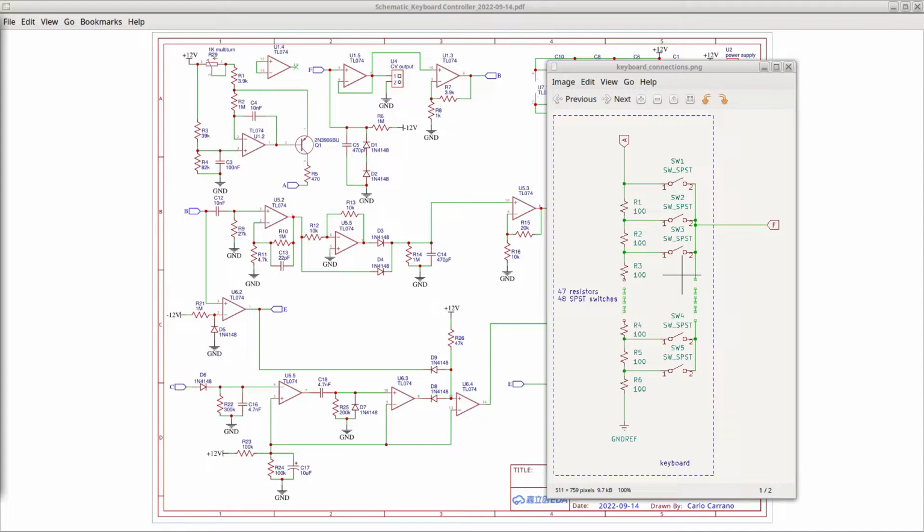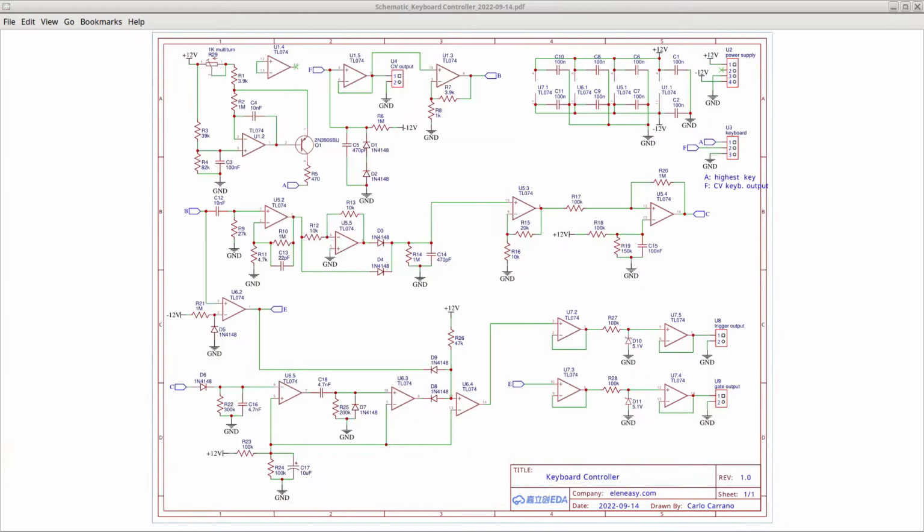We just need to make sure that the voltage between 12 consecutive resistors is 1 volt, because we know that every octave increases 1 volt the control voltage. Everything else is automatically adjusted, no need to do anything else. The current generator in this new design is a standard design using an op-amp to deal with the negative feedback and a transistor to generate the actual current. Take a look on my video on current generators to see the details of how it works.